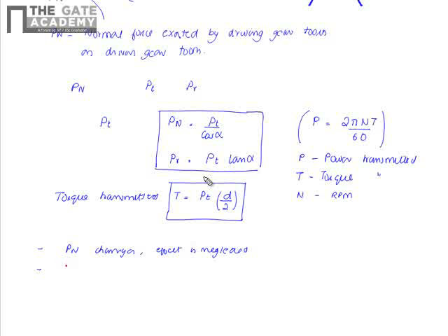For this analysis, we consider only one pair of mating teeth in contact. And this analysis is valid under static conditions, that is, when the gears are running at low velocities. So these are the basic assumptions in the force analysis. We use these basic assumptions to make the analysis simplified, otherwise it gets complicated.